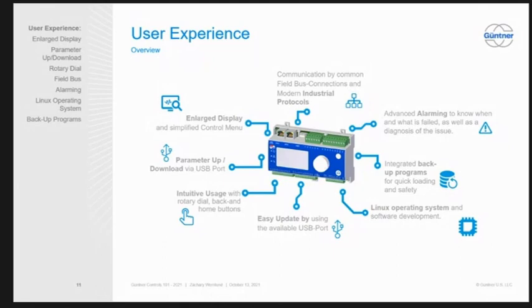So on our high side units, our GMM, once it's connected directly to the fan, programs the fan automatically. So a technician should never have to connect to it. On the low side, on the evaporators and stuff, that's a different story. That maybe has happened. It's rare, but it has happened. But when you're talking about our high side, our dry coolers, condensers, the GMM will program the fan directly. So there's no need for programming the fans.